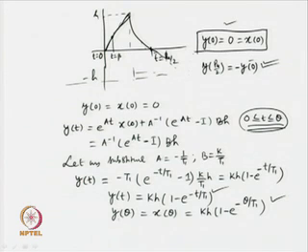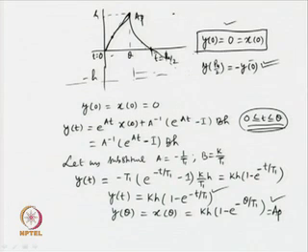Now, when time t is equal to theta, at that time the output we get is k h 1 minus e to the power minus theta by T 1. So, that will be the maximum output we get, which we denote by A p. So, this is equal to A p, and we know that we can easily measure the peak output signal, and therefore, that information can be made use of to estimate the unknowns associated with the transfer function model.